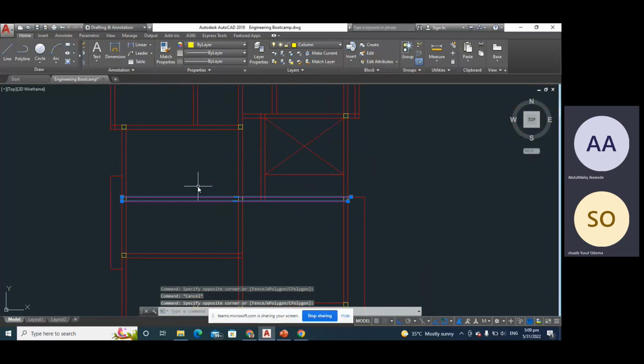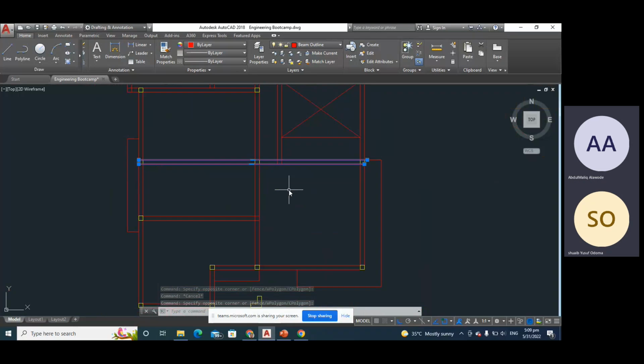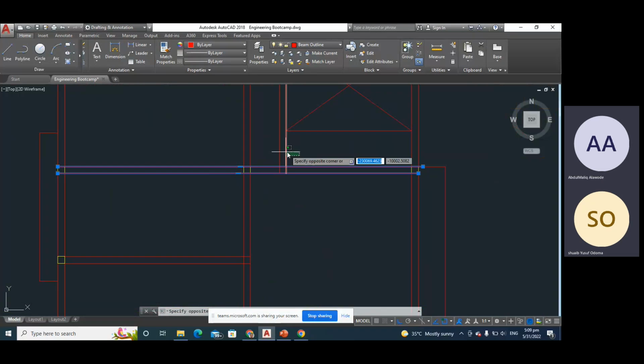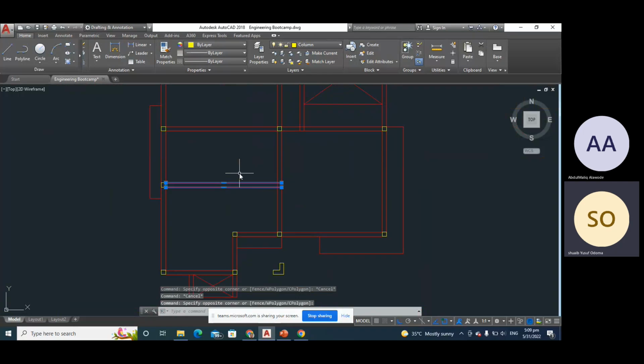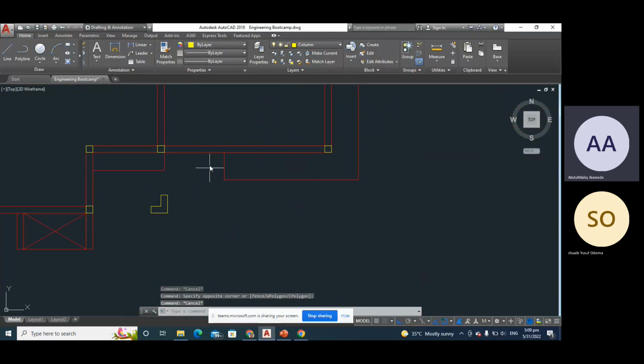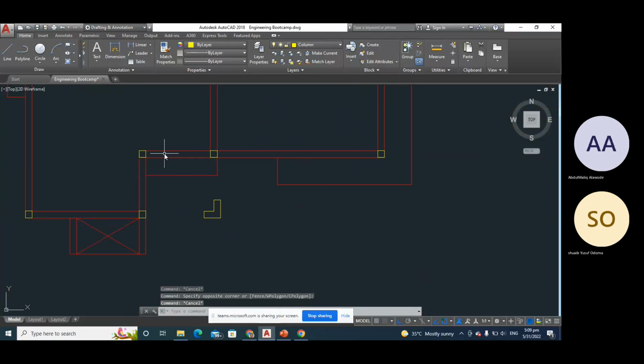That's that. This one is a very simple beam. It's a continuous beam with two spans. It's a two-span continuous beam. But at this point also, it is going to serve as a primary beam for this vertical beam. Now, this beam that I've highlighted is a simply supported beam. This beam is a continuous beam that has two spans and is supported by three columns.